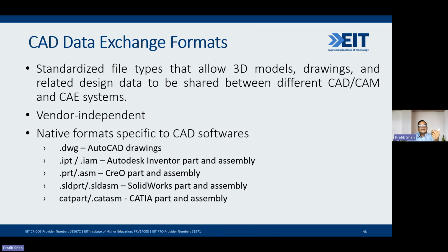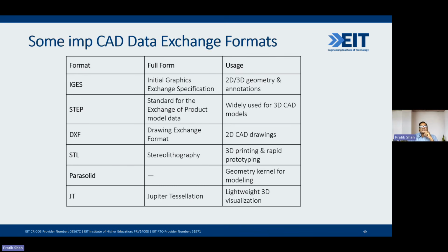And likewise, in order to facilitate input of these particular extension files into an analysis software, there are various CAD data exchange standards. These standards work similar to various standards that we talk about. They are acceptable by all the companies, and they are acceptable worldwide. Such data exchange standards are IGES, STEP, DXF, STL, Parasolid. So all of the CAD software will give you these facilities to convert into these exchange data formats.